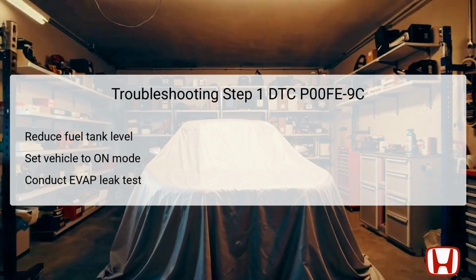In the first troubleshooting step, you'll need to reduce the fuel level in the tank to 3/4 full or less. This is crucial because the engagement of certain systems is more effective at reduced fuel levels. Next, turn the vehicle's ignition to the on position without starting the engine. This action activates the necessary systems for diagnostic purposes.